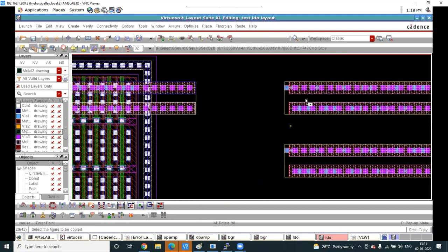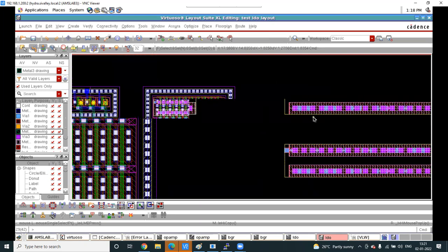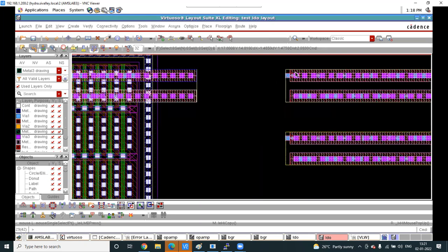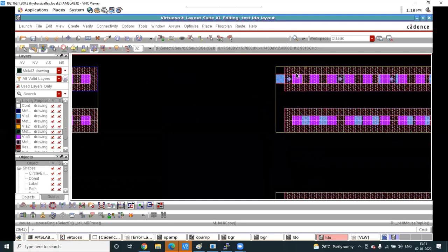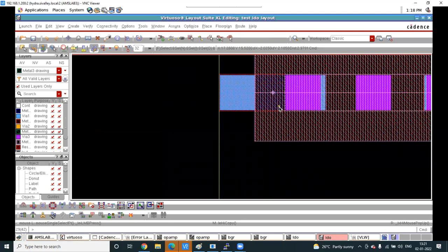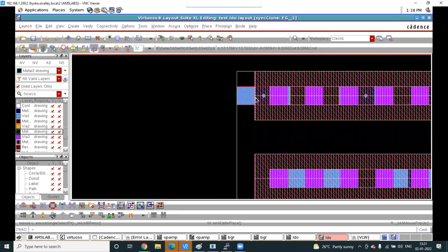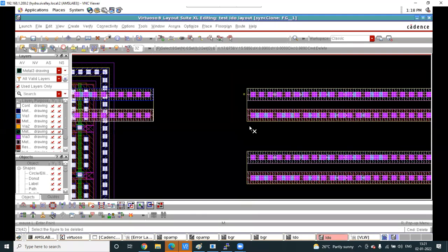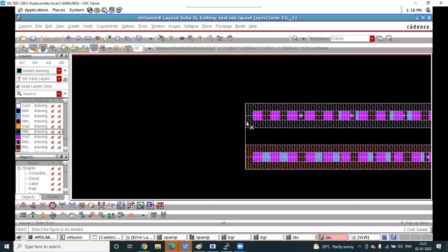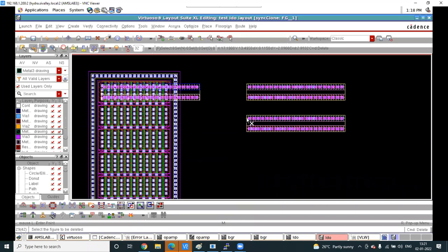Okay, so what is the advantage I actually want to show you? Suppose by mistake you are getting some DRC error and I need to delete. See, update all from. Okay, I delete something. So this VIA is deleted, so here also it will be deleted. Understand?